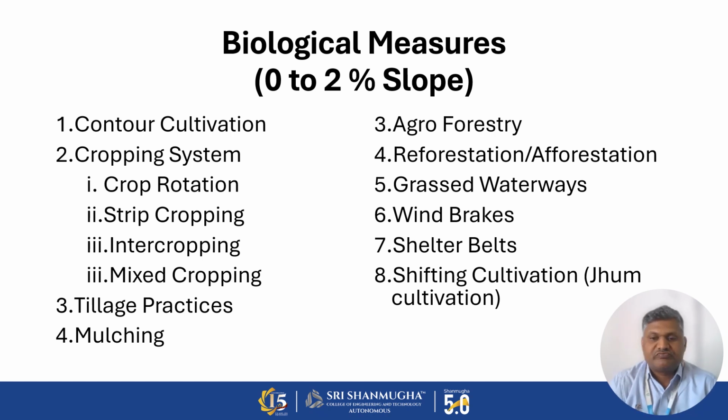The concept is that we cover the soil with covering material so that direct solar radiation is restricted, so that the soil water cannot evaporate, the water holding increases, and based on this we can also improve the scheduling of irrigation.